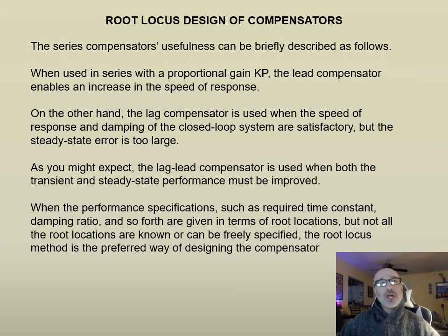But on the other hand, the lag compensator is used when the speed of the response and the damping of the closed-loop system are satisfactory, but the steady state error is too large. And as you might expect, the lag-lead compensator is used when both the transient and steady state performance must be improved.